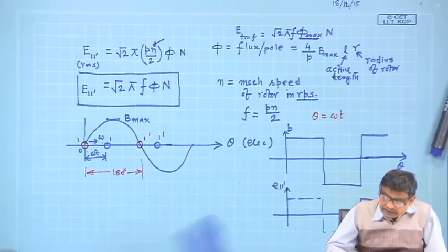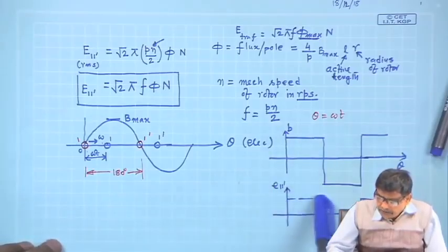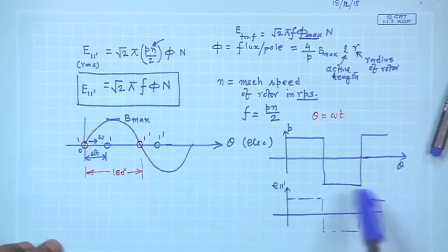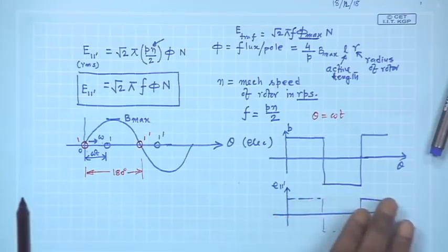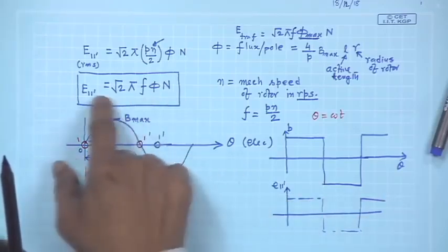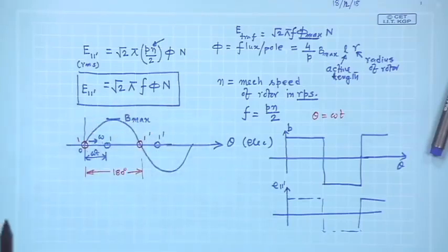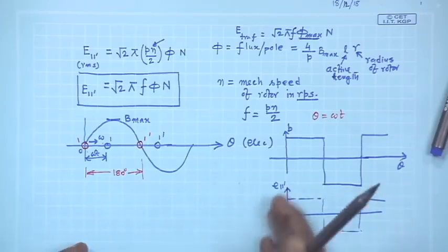One way of doing it is, this is rectangular, you find out the voltage pattern, which is also periodic, and simply Fourier analyze this. Of course, in this case the RMS voltage should not be calculated by this formula, obviously, because it is not a sine wave. But I know, given a periodic waveform, how to calculate the RMS voltage, etc.